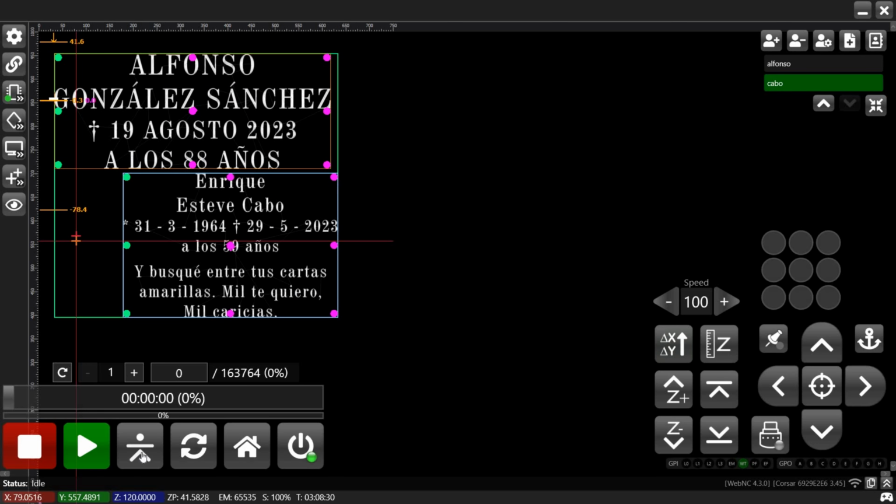For example, if we try to establish this surface higher than the machine allows, it simply will not start. The start button is inactive, and on the screen it is highlighted that we've gone beyond the boundary along axis Z. This is super convenient as the operator right away can see that the G-code cannot be performed under the current settings.